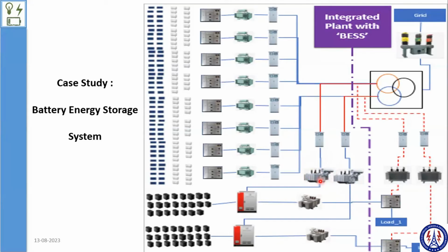So why do I use the 33 kilovolt transformer at the beginning, while I could go directly from the inverter output? See, the output of your inverters is 800 and the output of your PCU is 500. You cannot match that. Okay. Because of system and product availability I need to do that.